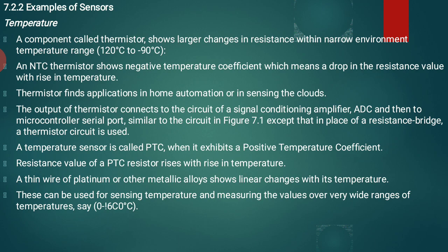Thermistors find application in home automation or in sensing the cloud. So whatever devices we are using in a home or in sensing the cloud may be stored in the sensors, the cloud sensing devices. The output of the thermistor is connected to a circuit consisting of signal conditioning amplifiers, an ADC, an analog to digital converter, and then to the microcontroller serial port.